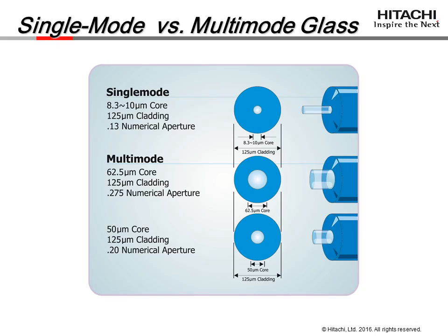There are two primary types of fiber optic glass available. Single mode, with a core of about 9 micron, is designed for long-distance applications and requires lasers as the light source. The other is multi-mode, which is designed for shorter distances. Multi-mode glass is available in both 62.5 and 50 micron. 50 micron, the newer type, is designed for faster network speeds such as gigabit and 10 gigabit Ethernet. Slower applications for multi-mode glass utilize LEDs as the light source.